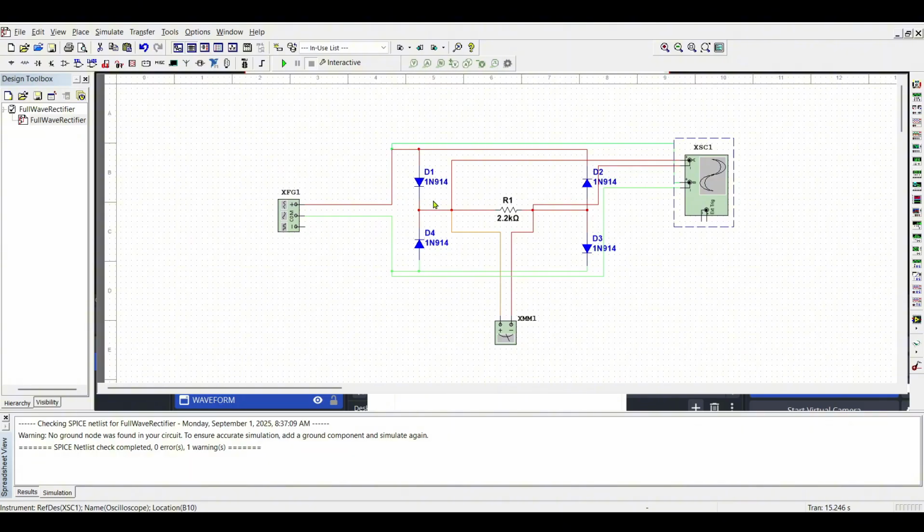We have these flat valleys, and then once it is on, it continually creates a positive output voltage that once again is slightly less than the volts peak put in due to the forward biasing voltage being used.